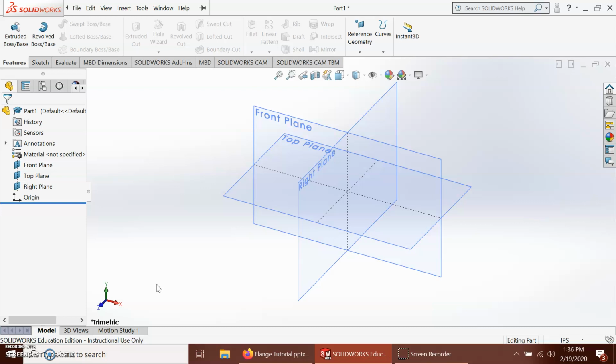And as we do this, you'll see SolidWorks has a good way of doing that because it's color-coded. If it's blue, it means it's not fully constrained. If it's red, it means it's over-constrained, which means you put too many constraints on it. If it's black, it means that it is fully constrained. And that's what you want to do. Every sketch that you make, you want to be black. You never want to leave anything blue. You need to put that together.